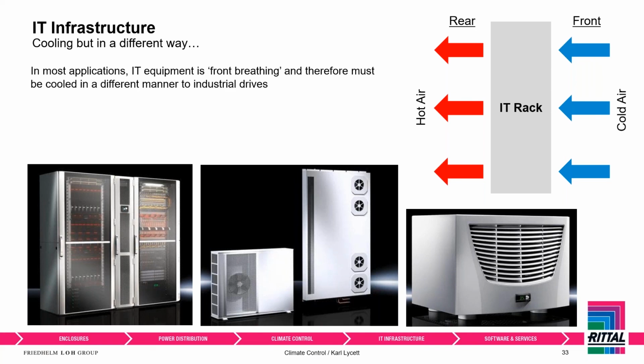Again, that's completely different to how industrial is done, because with industrial you just fill the enclosure with cold air, it warms up as it rises, and then it's either brought back into the cooling unit or it exits out the top through a fan or a filter.